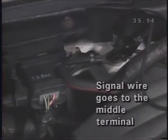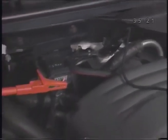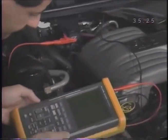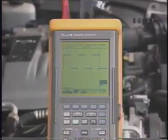The signal wire goes to the middle terminal on the sensor. Connect the channel A probe to the backprobe pin. Connect the ground lead to a good ground and turn the ignition switch on. Set channel A to DC coupling and press auto set.